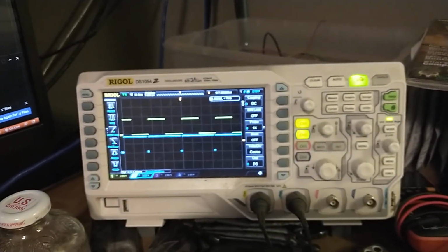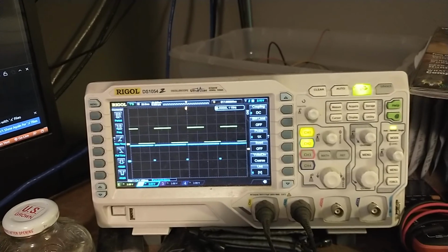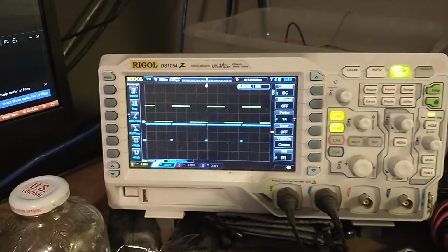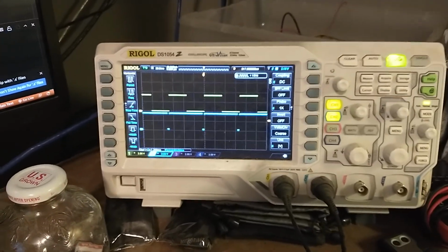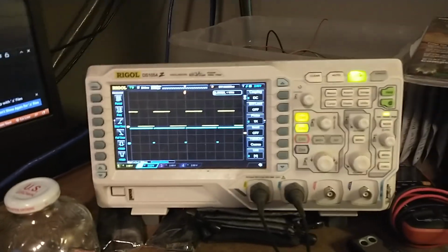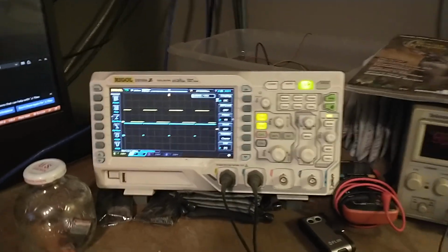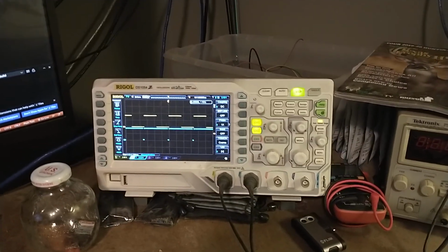See, we're triggering. If I take the crank sensor off, you can see we're still triggering based off only the cam sensor. So we're able to handle a fault with either the crank or the cam sensor and still operate.